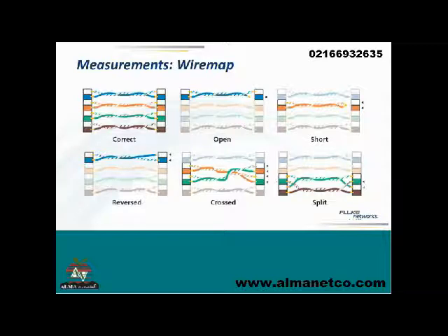And in fact, what will happen is sometimes people will wire up in the walls. They'll do things like cross the pairs to make things work better. Sometimes they'll also use separate pairs for the phone and other things, which none of this is standard. And while it's fine if the people who put it together are still working there, when somebody new comes along, they install something, it doesn't work, you don't know why. The last one I want to talk about is split pairs.